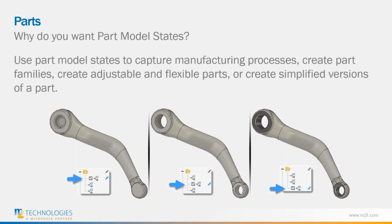So why would you want to use model states? Basically, model states empower you to create more flexible designs. You can create a part that has maybe different representations. These can be, say, a cast part that is then machined and finished off before you take that part and put it into an assembly. So it might have multiple different processes that you have to support to actually fabricate or make that part. So it's basically a way to make more flexible parts, simplified versions, or more detailed versions to support the whole process without the need of creating things like iParts. It's all contained in the single part file.